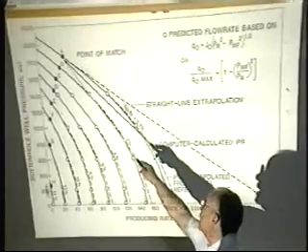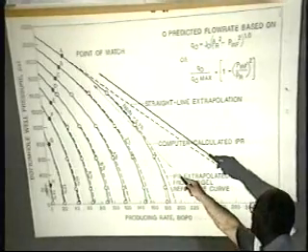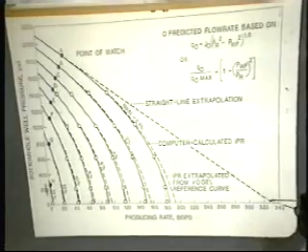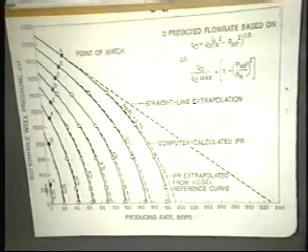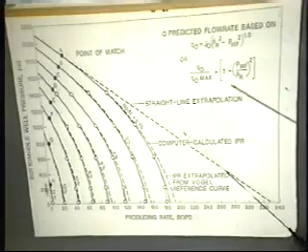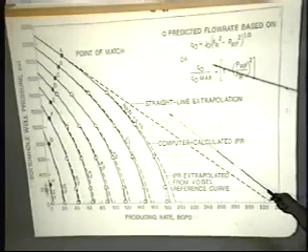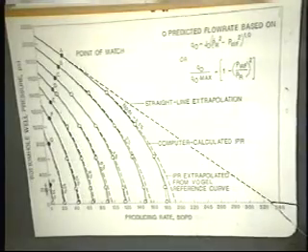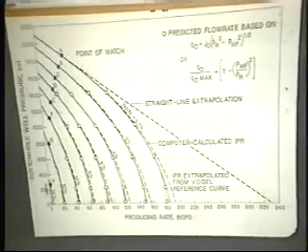If you draw a line through match point A and continue as a straight line, this would be the productivity index expressed in terms of a difference in pressure, i.e. delta P. And you'd indicate that well flowing at that rate, at whatever flowing pressure that is, has an absolute open flow potential of about 330 barrels of oil per day.